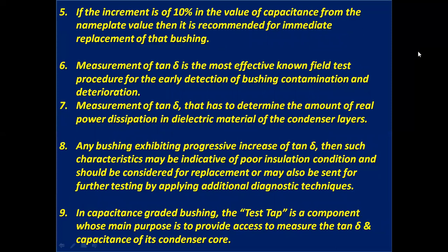If the increment is 10% of the nameplate value of capacitance, then it is recommended for immediate replacement of that bushing.